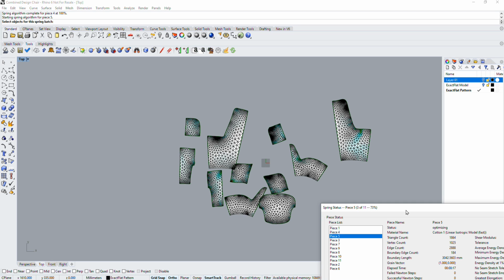Those would be areas of red and yellow, and that really represents elongation of the material, or areas where the material will need to be elongated or stretched in order to fit properly. Now, you don't really want your pattern pieces to have a lot of strain unless it is deliberately engineered to do so. What we prefer, though, is pattern pieces that really fit perfectly, and they are designed in such a way that the patterns have zero strain.